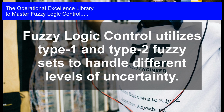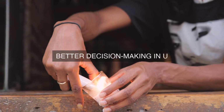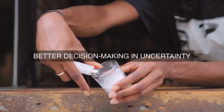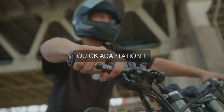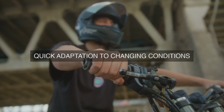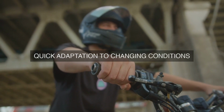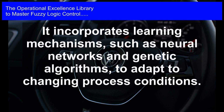This step is critical in fuzzy logic control, as it enables the system to produce a clear and actionable output despite the uncertainty and ambiguity in the process data. Fifthly, fuzzy logic control uses feedback mechanisms to adjust the control signal based on the system's response to the previous control signal. Feedback mechanisms, such as the proportional integral derivative (PID) controller, are used to fine-tune the control signal and ensure that the system converges to the desired state despite the uncertainty and ambiguity in the process data.